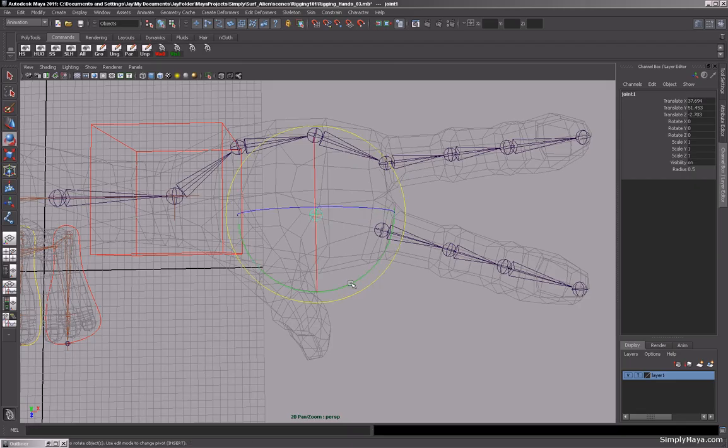And what I will do is I'm just going to rotate this joint axis actually. I'm just going to rotate this round. That's by hitting F9 and then the question mark up here, and then I'm just going to rotate the axis ever so slightly so the X now faces towards the forefinger here. And this is something that we're going to be just checking and readjusting joints as we go as well in this part of the tutorial. So with that done, I can turn that off and just hit F8 and hopefully everything should go back to normal. So that's all good.